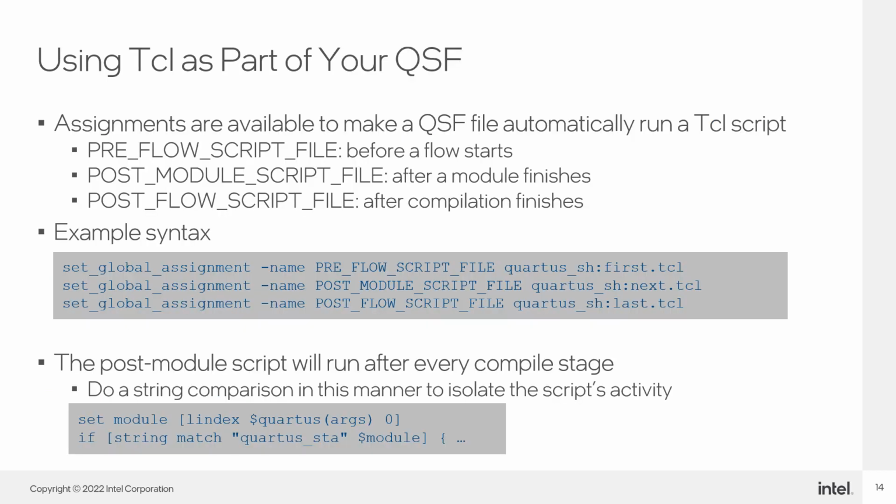The QSF is Tcl based and as such, can include Tcl commands and even source Tcl scripts to run. For example, if you wish to have your pin location assignments in a separate file, you can source that file in the QSF so that the assignments can be made. On this slide, you see some global assignments that allow various Tcl scripts to be run depending on what part of the place and route flow is happening.